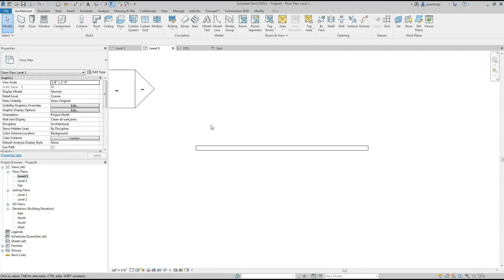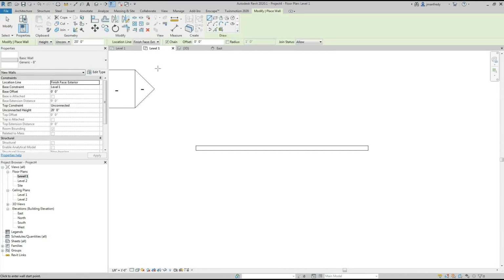Now you can also use other tools here. For example, there's an offset command. So when I say offset the next wall 5 feet, 6 feet, and besides, instead of drawing rectangles and squares of different shapes, you can also use this. This is a very popular command, pick lines. That means whatever you pick, it'll draw something the offset distance away.